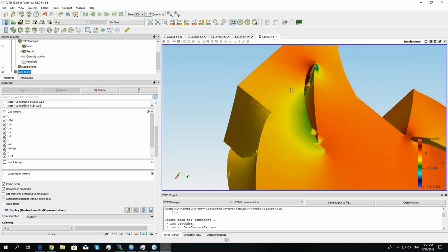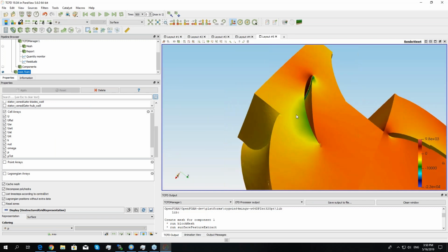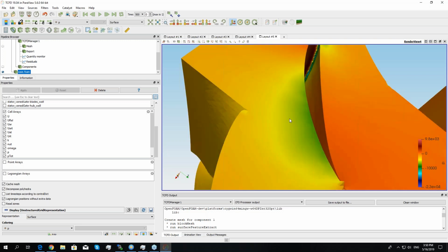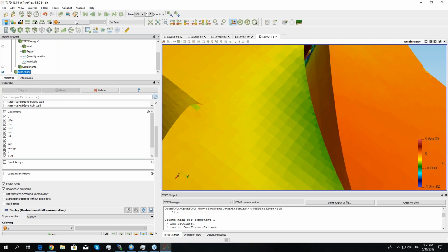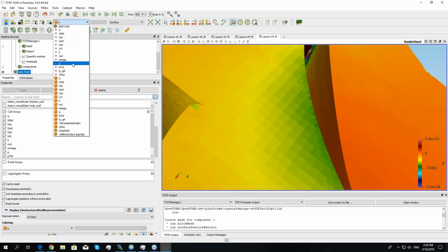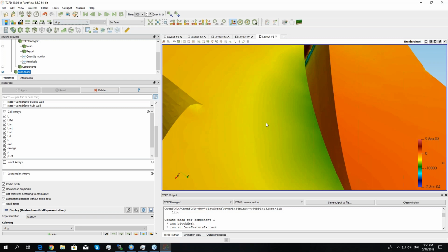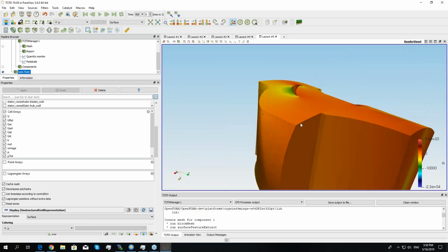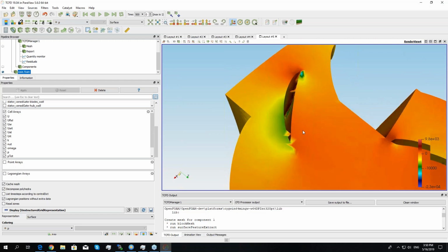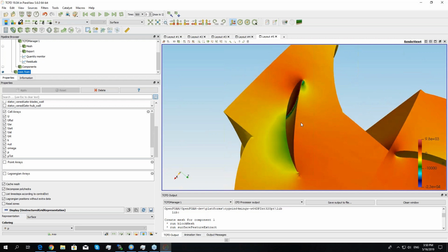So it seems that the data are much finer than it is in reality because of just the interpolation. So one visualization aspect is that the point field looks much more fine than the cell fields, but it's just the interpolation. It's nothing to do with the accuracy of the results, of course. So this is the cell data and point data.